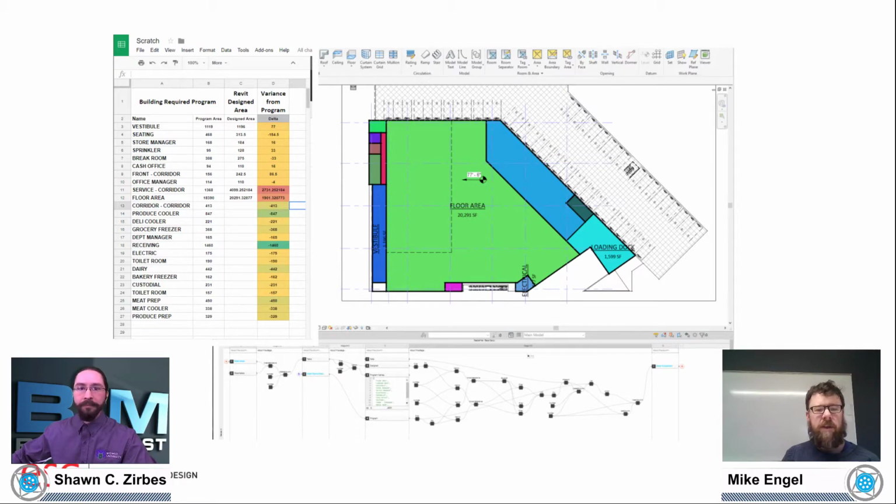It's just this: you put your design program into a spreadsheet, and then using Dynamo and computation in the back end, you have this ability in Revit now to place rooms and do that free sketching form of moving shapes around. What's happening essentially is I'm just cross-referencing what I'm modeling to what I'm programming and letting all of that happen in the background. So I, as a designer, can push and pull in a very free format but still get that feedback of understanding what my design decision is and how it relates to the requirements on a very immediate basis.